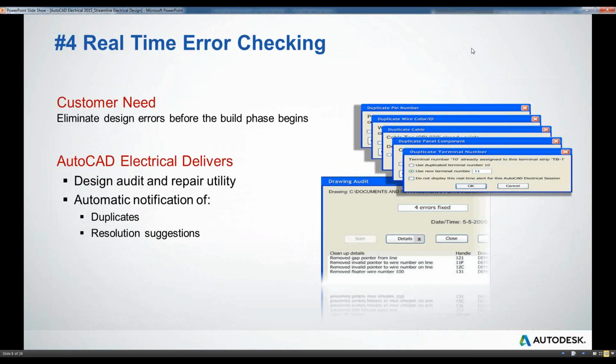Error checking. As I go through and create these designs, AutoCAD Electrical is checking for me in the background, working intelligently because they're not just lines, arcs, and circles. They're actually intelligent wires, right? So it's actual real wire. It's an actual schematic. I'm building that information so it knows the relationships to those components. So, great error checking.